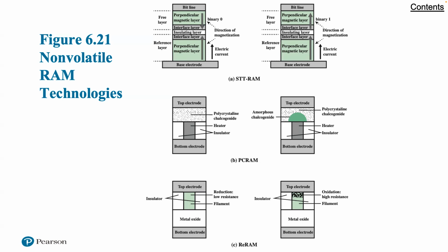So this storage capacity and programming of MRAM arises from the magnetic tunneling junction, MTJ, in which the thin tunneling dielectric is sandwiched between two ferromagnetic layers, as I said. One ferromagnetic layer, the pinned or reference layer, is designed to have its magnetization pinned, while the magnetization of the other layer, the free layer, can be flipped by a write event. An MTJ has a high resistance if the magnetization of the free layer and the pinned layer are antiparallel.